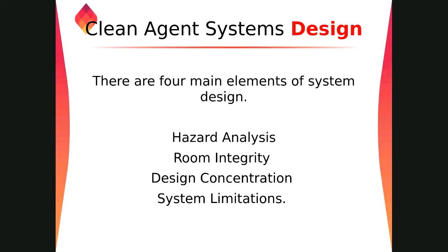Now we come to clean agent system design. This is just a basic overview of the design. For designing the system, we have to know the hazard analysis and room integrity. The one you discussed, that the CO2 system came and destroyed the room. Of course, room integrity has to be designed very carefully. Then we have to go for the design concentration, and then finally the system limitations. What are those system requirements at all?